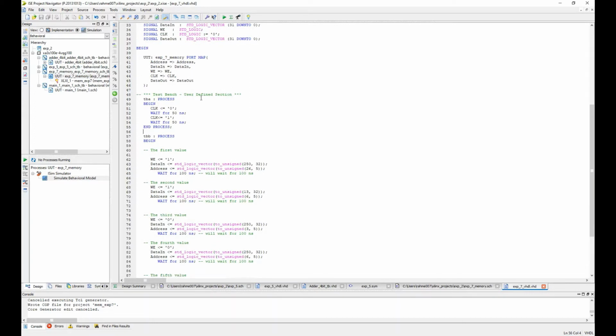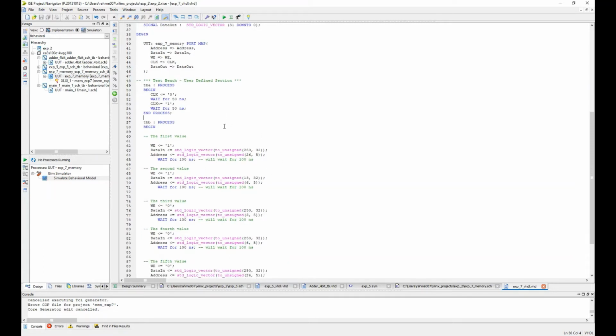Then you have to go ahead to the test bench part. In this part, you can put a different process for your clock signal and for your data inputs. Here, I have declared a clock signal with this process, and in this process I just put the time period as 50 nanoseconds. If you want to make clock signals with the not option, like the inverter option, you can do that, and then you can have the clock period. What will be the clock period for your clock signal?